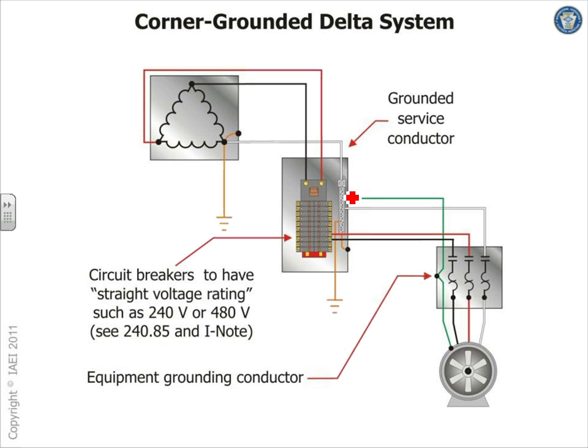So they pull this one and one of the phases right here and land it on my lighting fixture. Now, typically these are 240 or 480, so you've got 240 across a light that's rated for 120, and you burned it. But it's legit, it meets the code. It's just not a good idea.